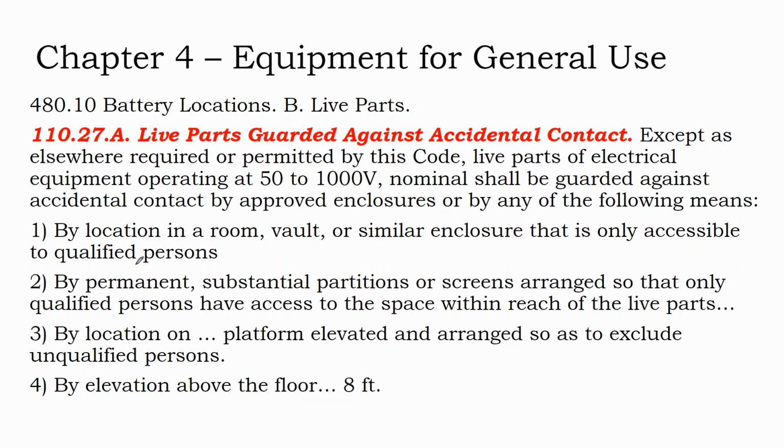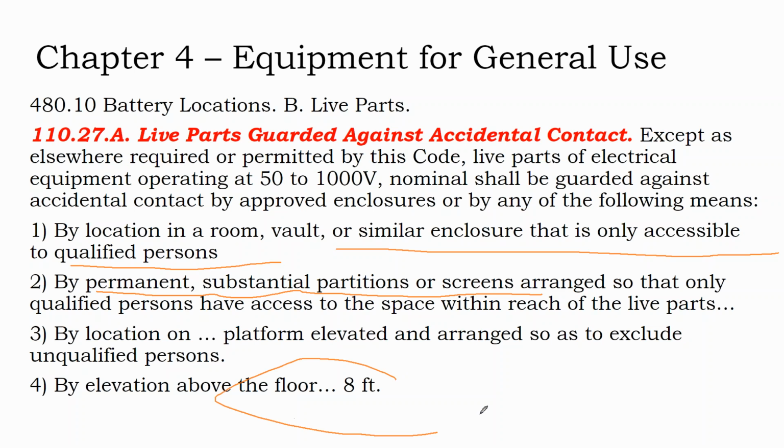But you can locate batteries in a room that is only accessible to qualified persons, or you can put permanent and substantial partitions or screens between the battery bank and the battery area. Or, traditionally, keep them 8 feet of clearance off of the floor on an elevated platform.